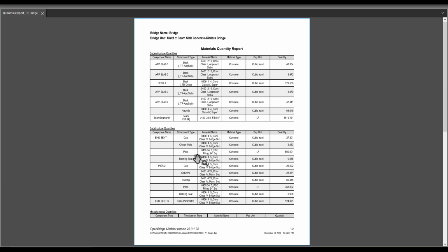Likewise, as previously mentioned, when you do use solids modification, it's not going to show up yet because we've not incorporated that into this model yet. But oftentimes the solids modification may not be fully reflected in the quantities, so it's just something that needs to be verified when completing your quantities versus the quantities directly pulled out of the program.